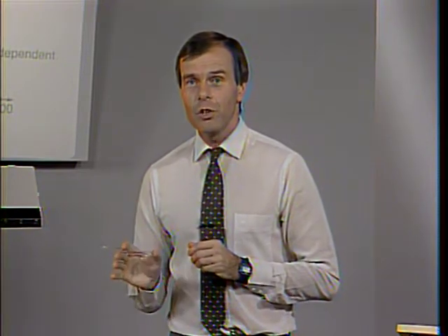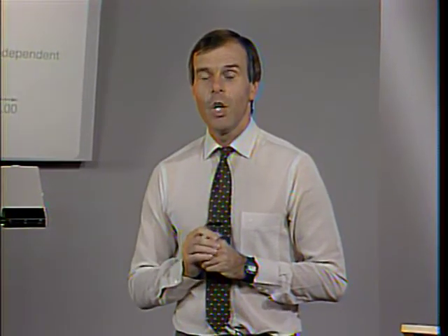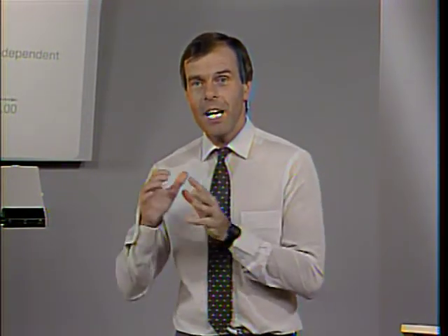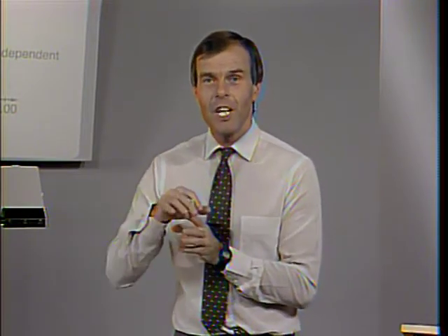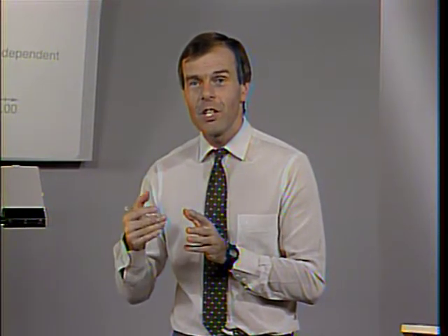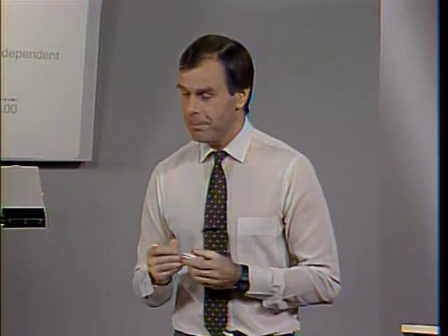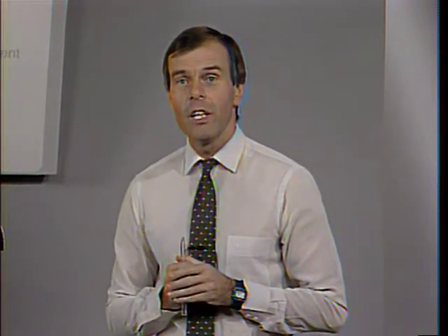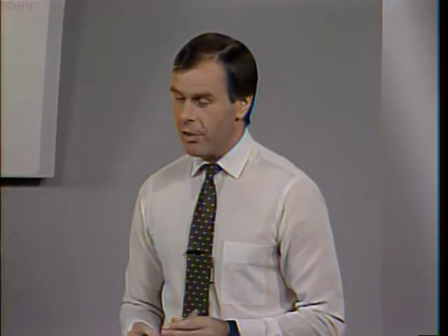So in this particular solution, when we dealt with the deformation-dependent loading, we kept a symmetric stiffness matrix on the left-hand side, but we updated the load vector t plus delta tr in the notation that we used in our earlier lectures for the configuration and for the iteration that we actually are dealing with. And when we did so, we found that to obtain this total curve here, we needed about 20% more solution time than for obtaining this curve here. So taking into account the deformation dependency of the loading in this particular example just meant 20% more solution time with the computer program. Here on the next view graph now we show pictorially how the cantilever has deformed.